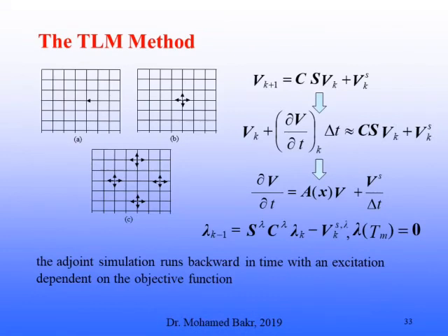This approach does not only apply to circuits. We did extend that to numerical electromagnetics. We applied it to the transmission line matrix method. In the transmission line matrix method, you fill your computational domain with a grid of transmission lines, and you try to model how the electromagnetic energy is spreading through scattering and the connections in this network of transmission lines. I'm not going to get into the details, but starting from the original simulation of the TLM method, there are derivations. You can look up some of my papers on this.